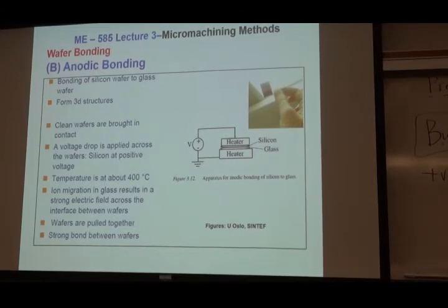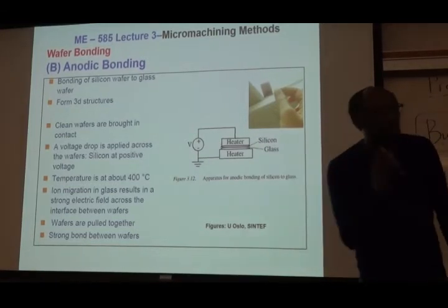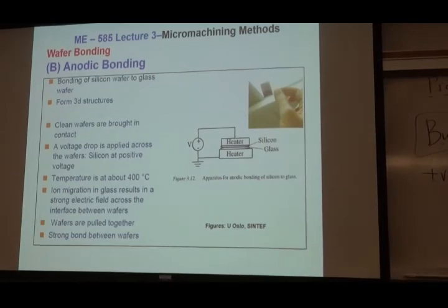So then you go to anodic bonding. In anodic bonding, usually it's silicon with glass. In fact, I didn't bring my glass substrates. You could get this in quartz, glass, what have you. It's particularly for biological and chemical applications, where you need a cover. You're passing blood and liquid and all that kind of stuff, and you want to be able to see things, cells moving and all that.